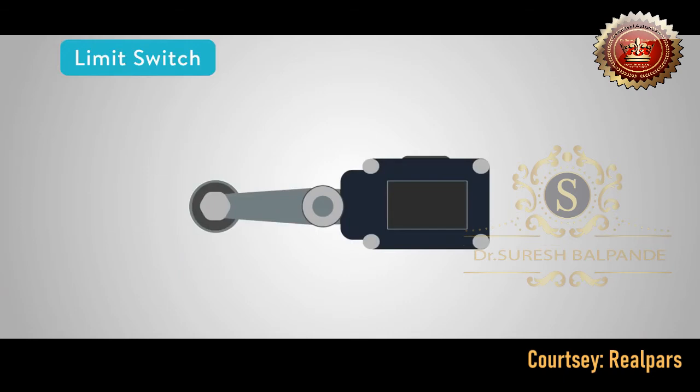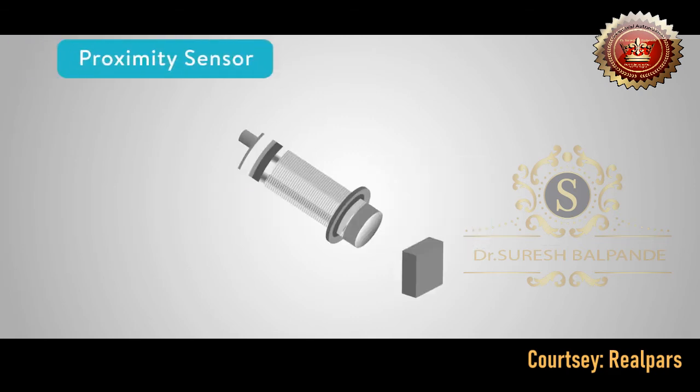First, as mentioned before, mechanical switches of various kinds are still around. Limit switches are still used in ugly, dirty environments thanks to their armor-plated construction. One big reason they have become less popular over the years is that they're huge compared to many of the other sensors available. Proximity sensors, very often called proxies, are used for detecting close metal objects using magnetic fields. In many environments, these have replaced limit switches in position sensing applications.